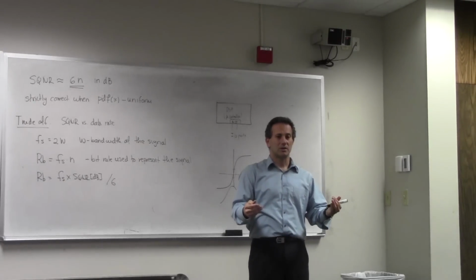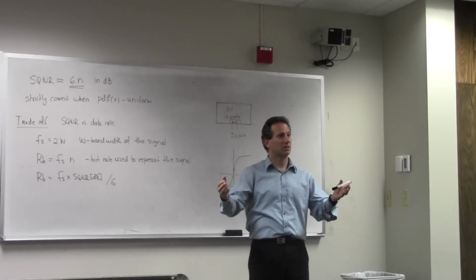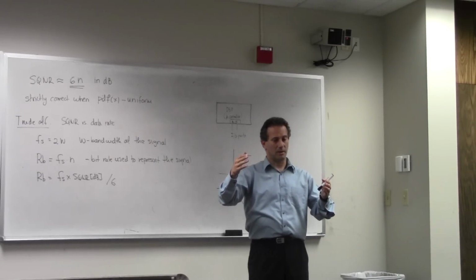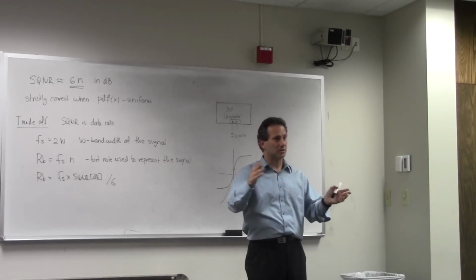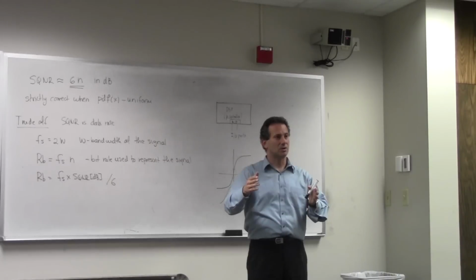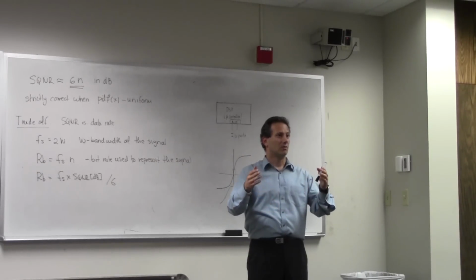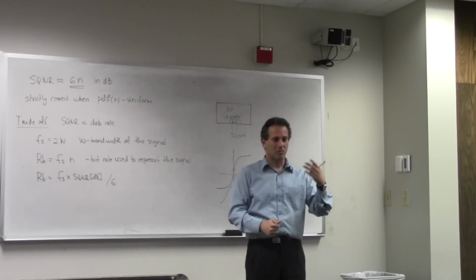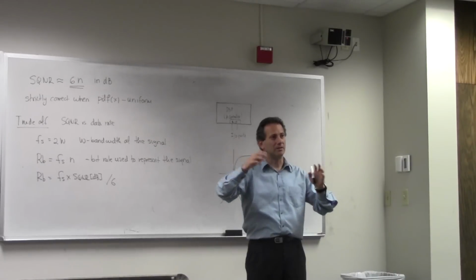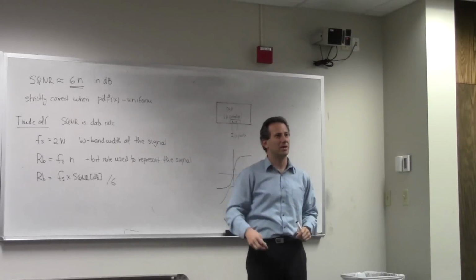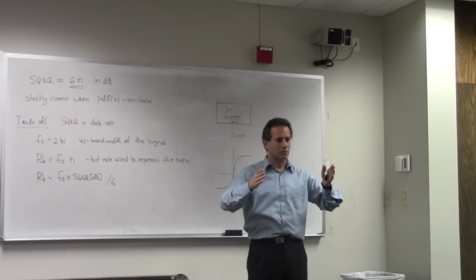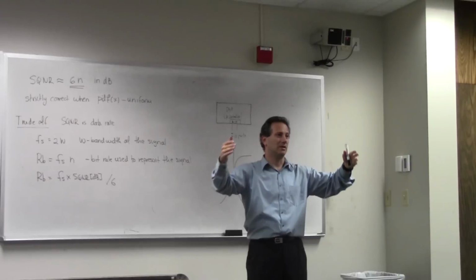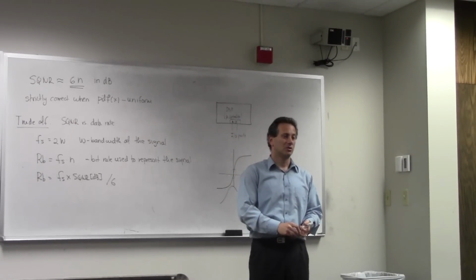And what that does is, if you have a system that required, let's say, a 12-bit quantizer to operate properly, now through this amplification with these nonlinear amplifiers, the compression and decompression, you end up getting the same SQNR, but now with 8 bits, which gives you a much lower throughput requirement on your communication system. And remember, in our world, bandwidth is everything. Right? You would trade pretty much all the processing on 2 ends just to save the bandwidth, because bandwidth translates into money. If you always go through a shared channel, and the smaller the bandwidth you give to one user, the more users you can put on that, and then you can get paid more for the same resource. So that's the idea here.